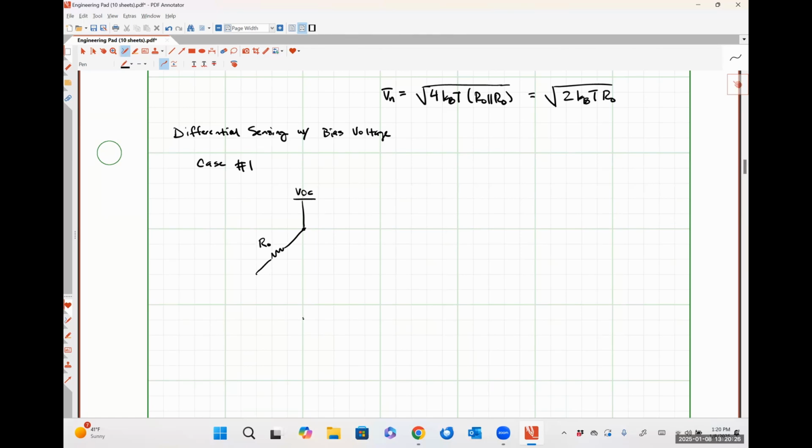And we're going to have three reference resistors, R naught like so. And here is our piezo-resistive sensor. I'm going to put ground down here. We're going to call this guy V1, call this guy V2, and our output voltage V out will be defined as V2 minus V1.